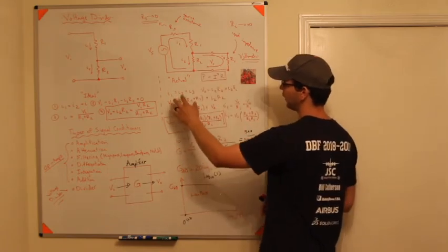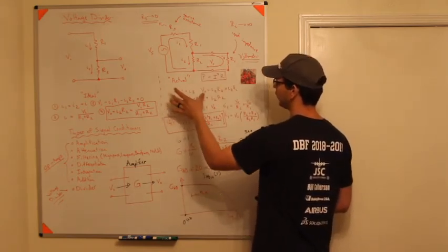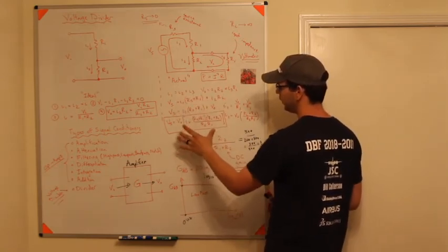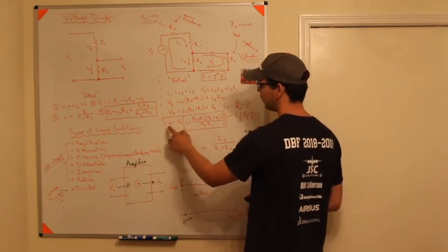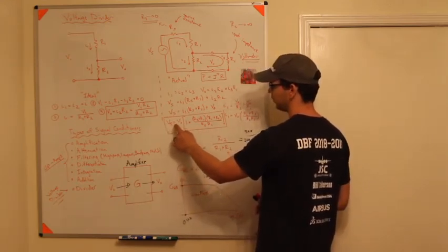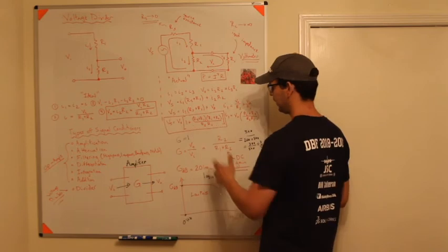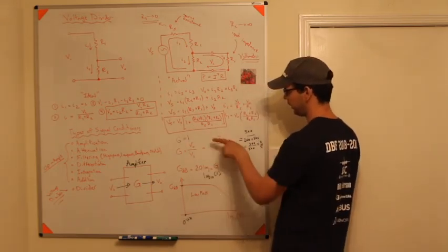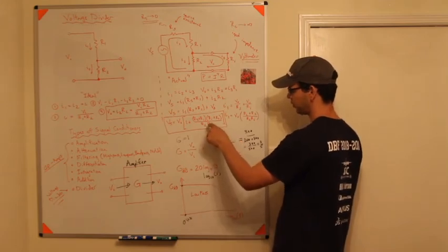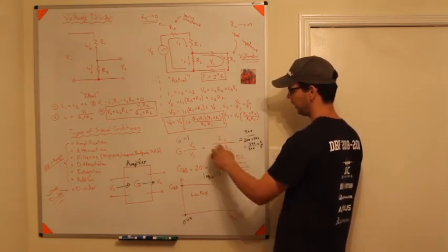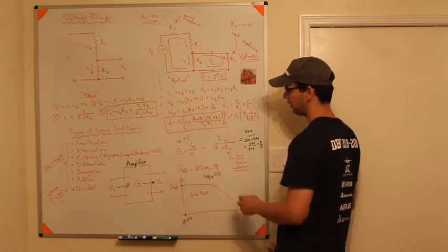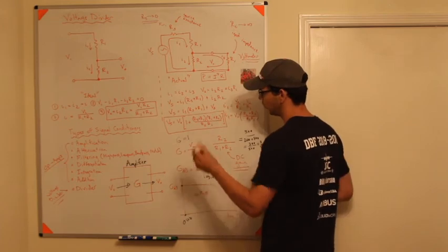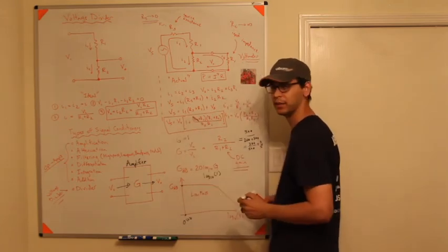And if you put the whole thing together using Kirchhoff's current law and voltage law and all those different laws, you get this really long equation here, which says my source voltage is equal to my output voltage times this. Now, if you look at this equation, I'd like this term to be the inverse of this. So I want R2 to be on the bottom by itself, and I want R1 plus R2 to be on the top. Now, the only way for that to happen is for RS to go to 0.